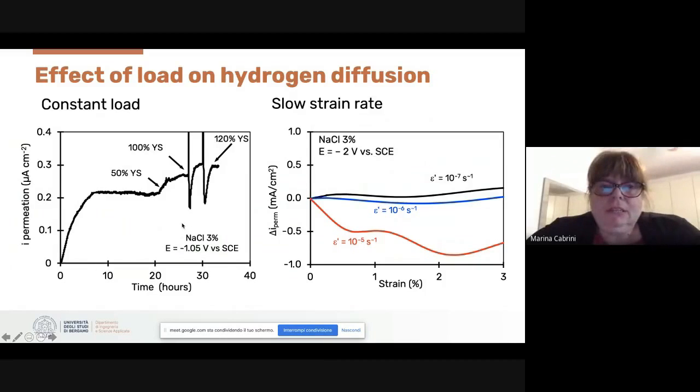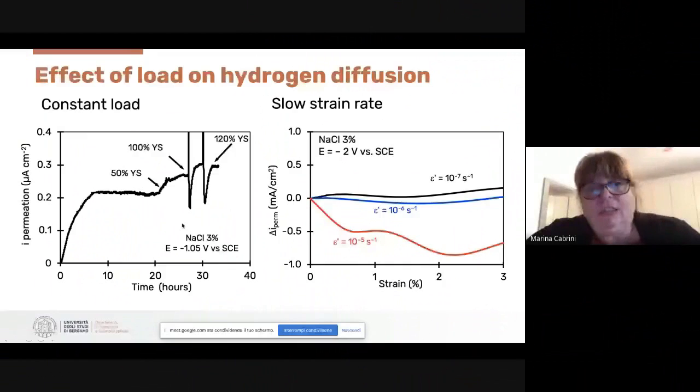This is only another effect, in which the passive film is suddenly in contact with the anodic compartment and is immediately oxidized. This is the initial sudden increase of anodic current.